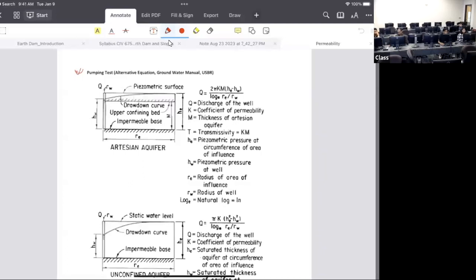For clay, there are other ways of getting very good results. One is by doing the CPT. CPT is a terrific test for clay. It works really great. If you push it and then look at the time difference, that gives very good results using the CPT.